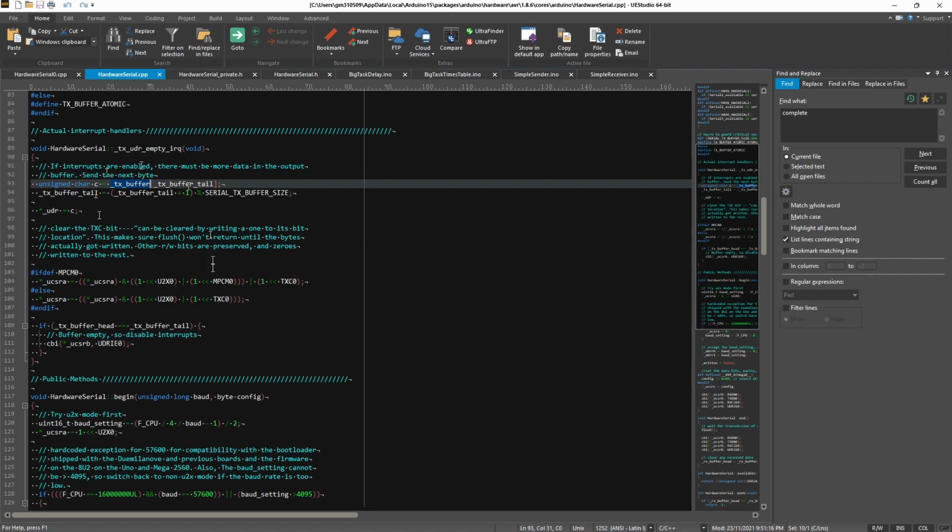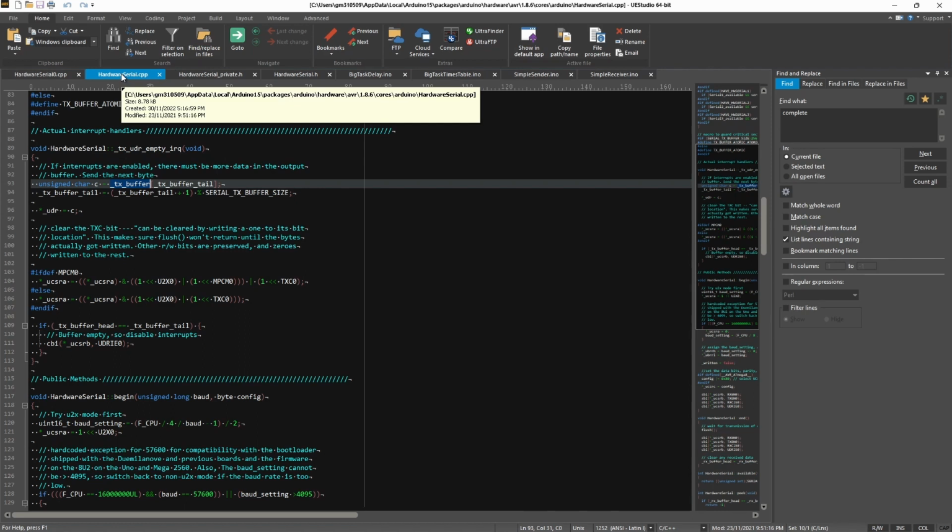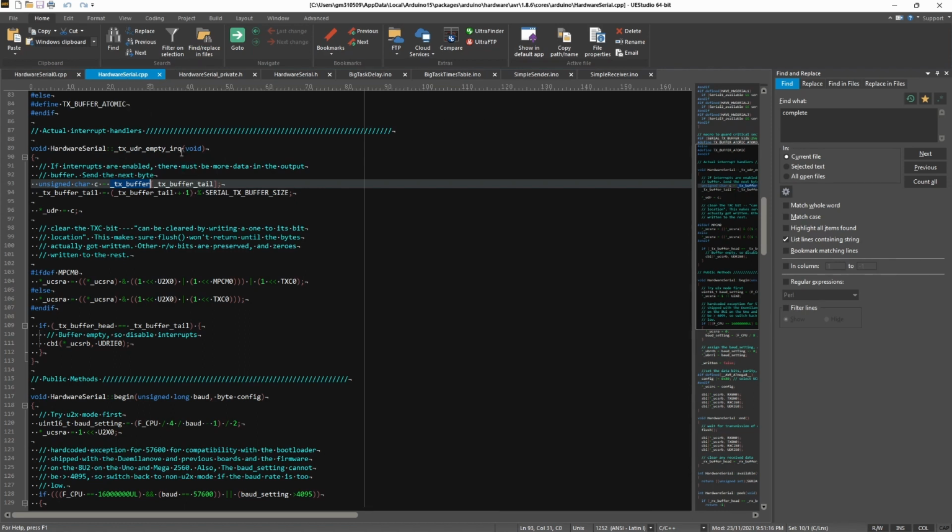well, effectively this has peeled off some characters from the buffer and allows it to return. And so what you see is when it's sent enough data and the remaining print messages can fit into the buffer, then the print line will return and then the LED will start blinking again. As I said, it's a little bit hard to see because it happens very quickly, so I might not include that, but that is something you can do. And when I put this code on the website, I'll put both examples so you can try both at home if you want to.